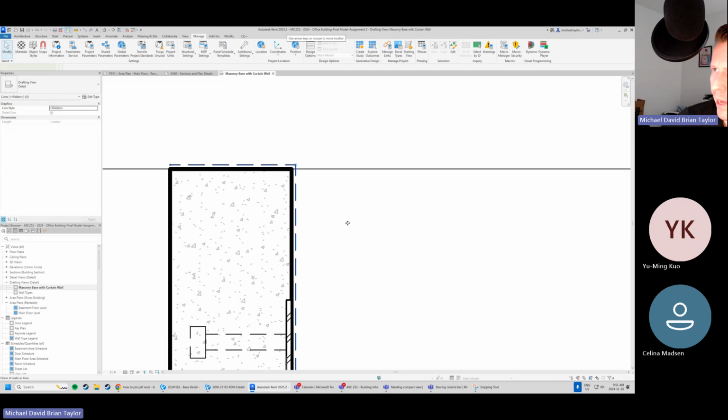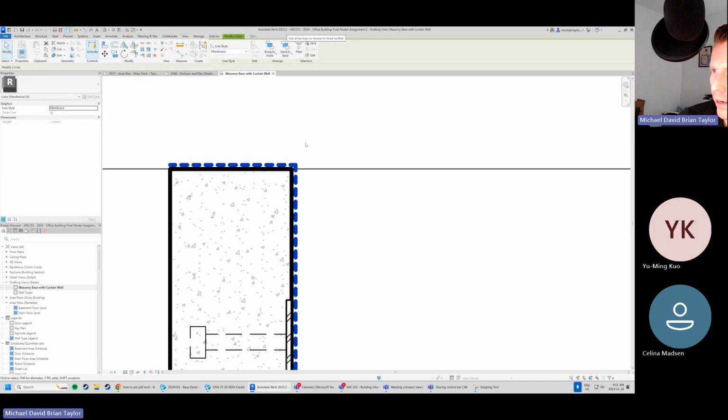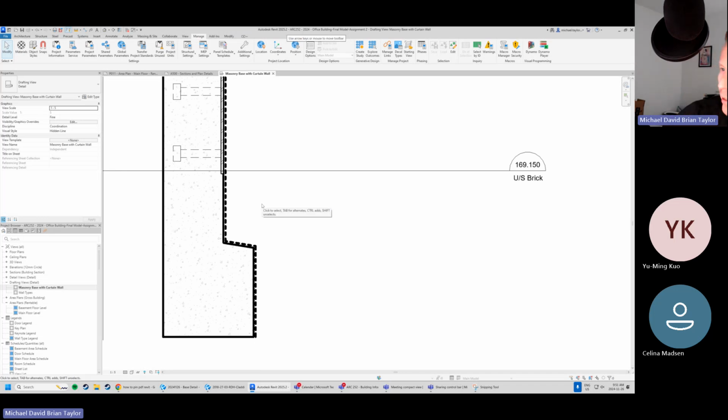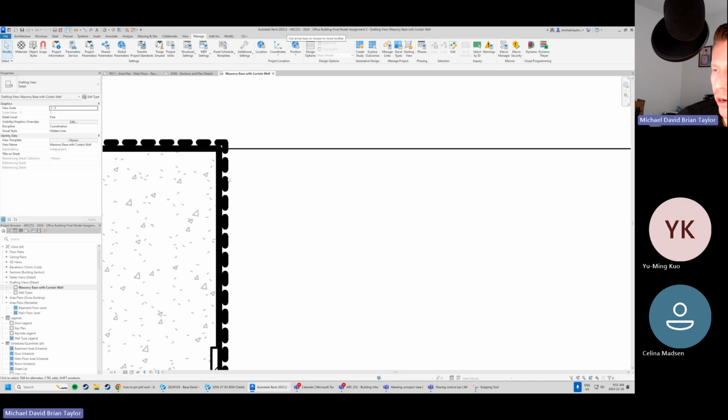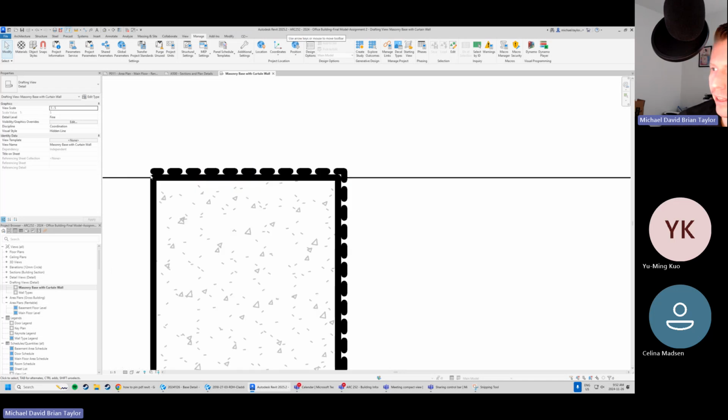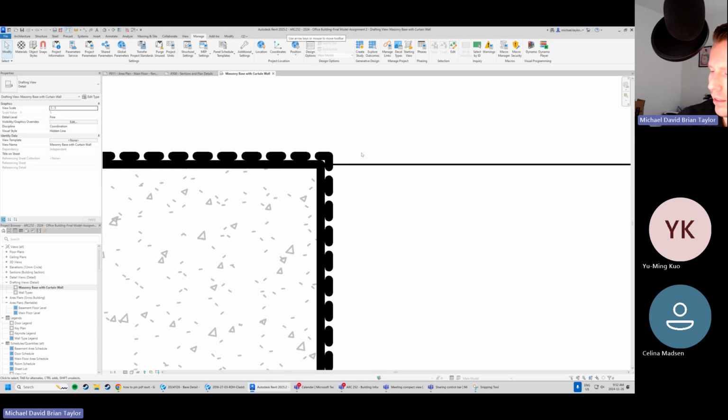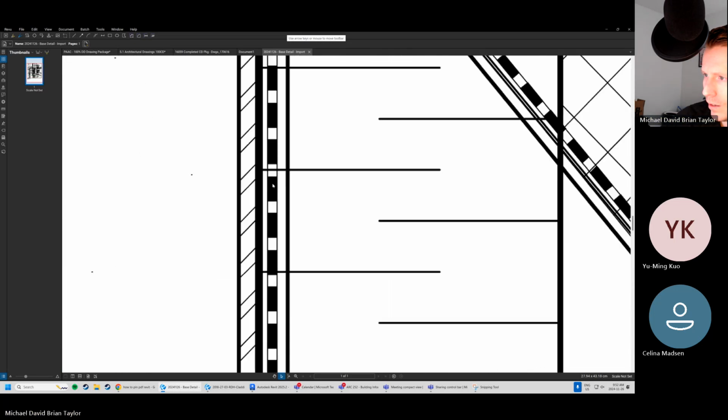And by Tab select here, we should see a new line style emerge. So membrane, right? Pretty thick, looking good. I leave it to you if this is exactly what you want. I know that Revit has a habit of, you can see everything is rounded, and I feel like it gives the drawings a little bit of a cartoonish element. It's unfortunately pretty baked in. That's okay. I would argue that's one of the big differences between AutoCAD drawing and Revit drawing: you can see everything has these curved edges, right? So anything that would normally be drawn in AutoCAD as these really crisp, square-like things becomes these rounded elements.